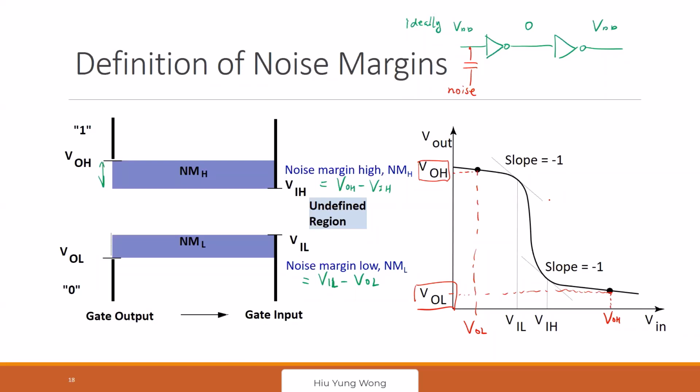Right. Now, what if we have noise? Well, the noise, if I increase VDD by a very high value, the output is 0. No problem. I welcome this type of noise, except for reliability or some leakage latch-up current issue, right? The one possibility is this will reduce my value by NMH, coupling noise. This is possible, right? You have a capacitor coupling to another wire. Another wire has a rapid transition, and this one has an RLC drop. Then the input becomes VDD minus NMH. What will be the output?